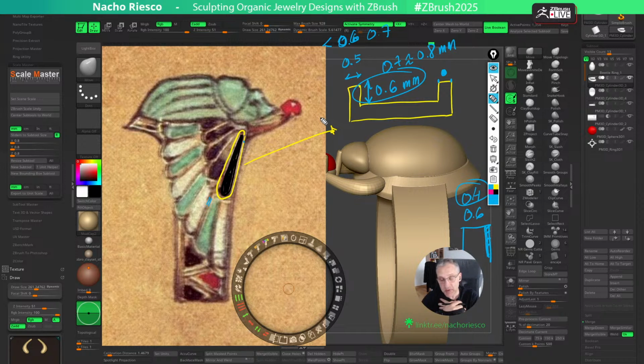Okay, it's very difficult. This is one of the most challenging things about jewelry, that we are using a very small amount of material and very small measurements. Sometimes we learn from the errors we make while making different designs, and we start learning our own numbers, our own distances and thicknesses, and so on. The height of the walls is 0.6 millimeter, or maybe the thickness of the walls is around 0.5 millimeters or less if possible.